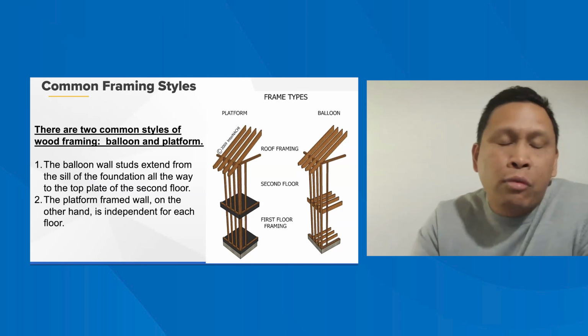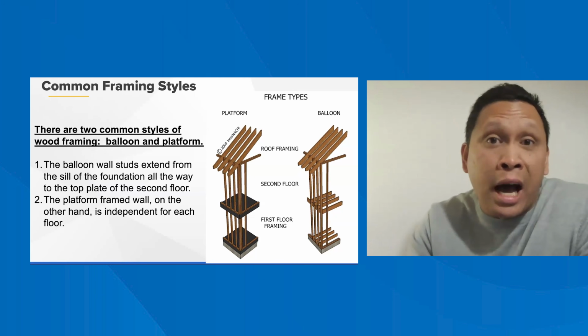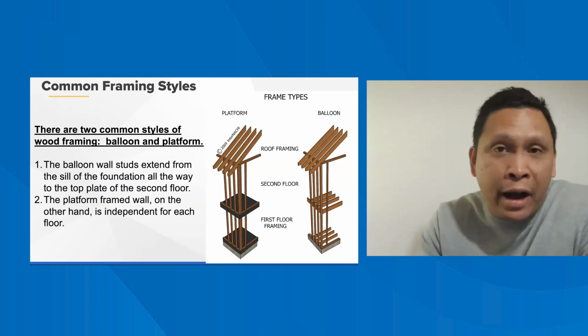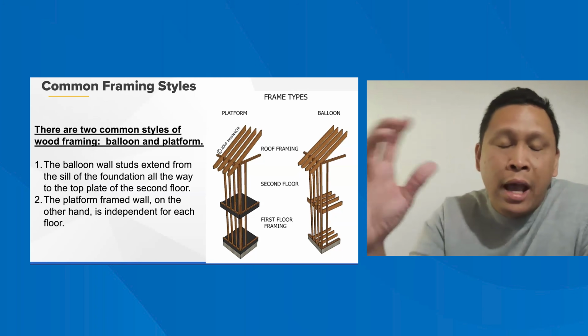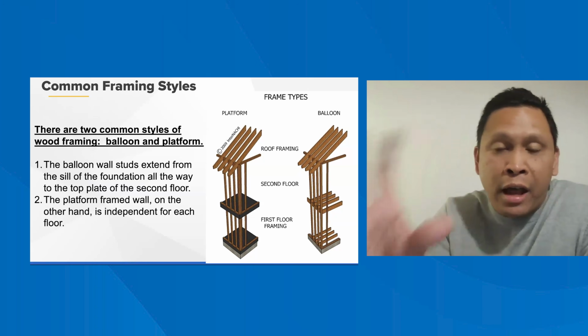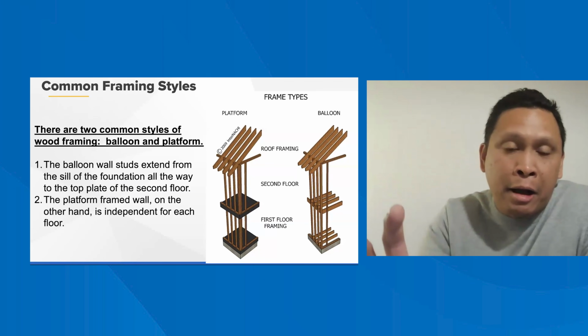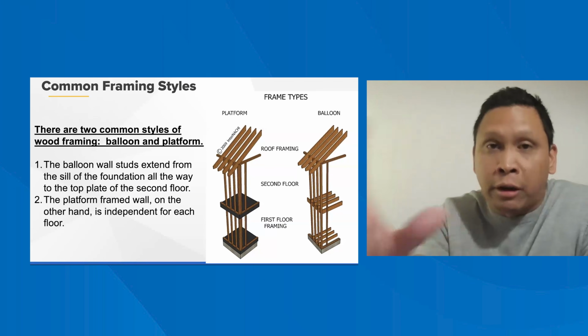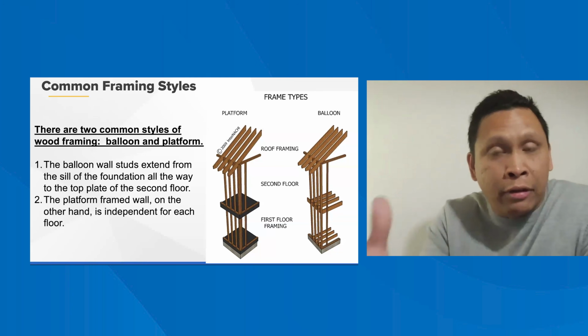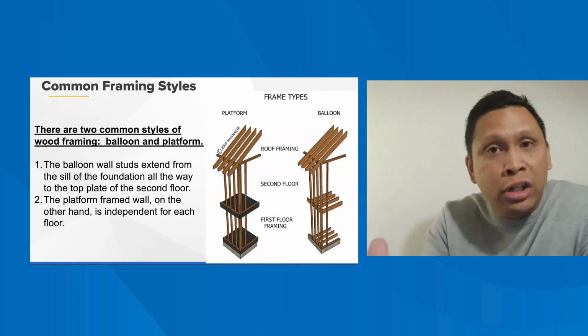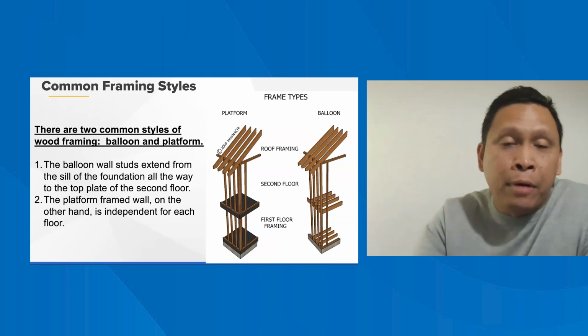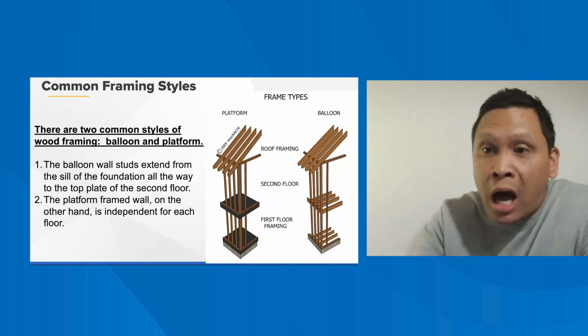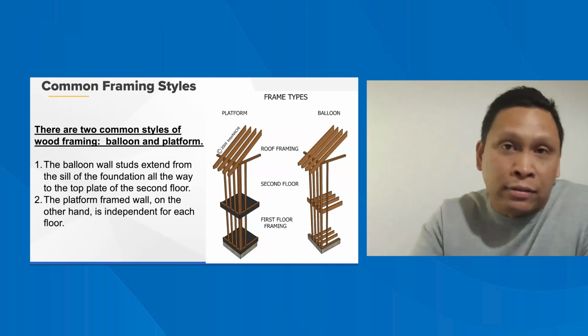Fire stops, another way to describe it, is a fire blocking system. Oftentimes you'll see a contractor, I also call it a builder's vendor, or a builder, taking spray foam. Oftentimes it's going to be orange in color. The colloquial term is fire block, but it's actually called draft stop.